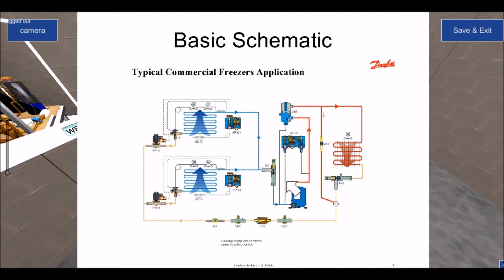That means that when the back pressure gets to 0 bar, the electrical contact will open. Once that opens, that kills the power to the compressor and the compressor stops running. As soon as 2 bar pressure comes into the back pressure onto the bellows, that 2 bar pressure will force the contact to close because it will be higher than the spring pressure. Therefore, once the contact closes, electrical feed returns to the compressor and the compressor starts.